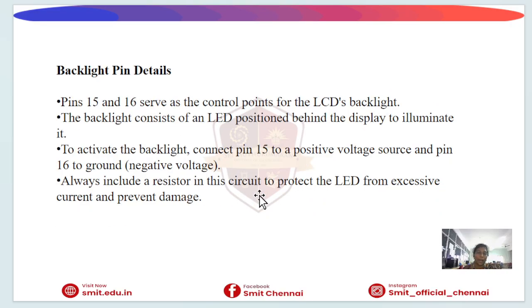The next one is the backlight pin details. Pins 15 and 16 serve as the control pins for the LCD's backlight. The backlight consists of an LED positioned behind the display to illuminate it. These pins are the backlight pins, which control the LCD's internal LED backlight. So these are very important points.